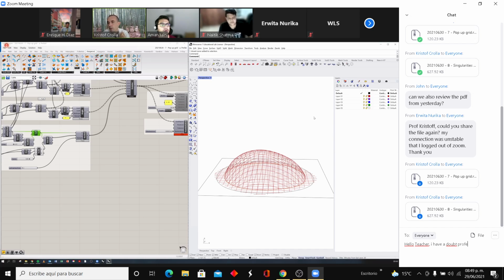But in principle, the only thing that defines the geometry that we have arrived at over here is the topology of the grid, which means its number of cells and the distance in between them, and then the end parts, how long they are, and then the exact location of the anchors, which here are presumed to be hard fixed on the ground. And there, the forces are not even as well. If you would build this one from bamboo, it's possible that it will have its edges popping up, because maybe it's pushing harder in the middle than it's pushing at the sides. So the anchors are quite essential.